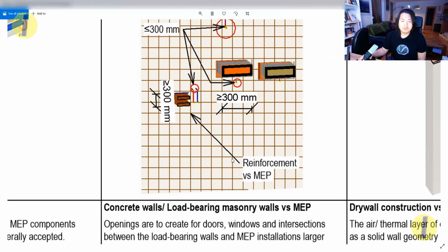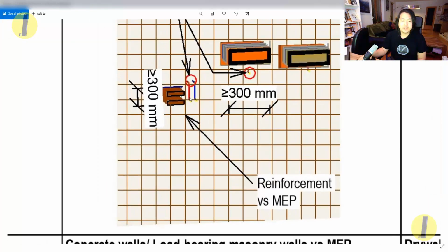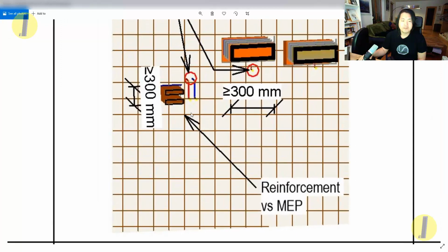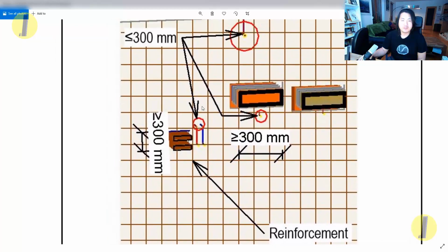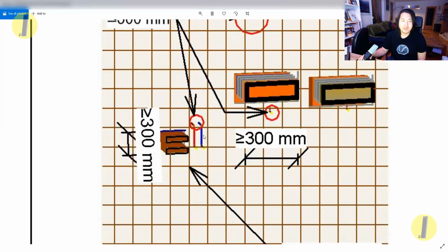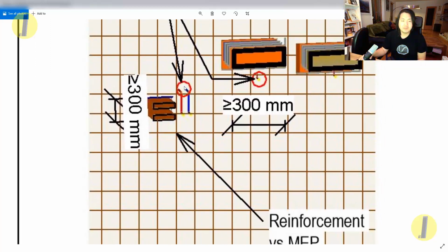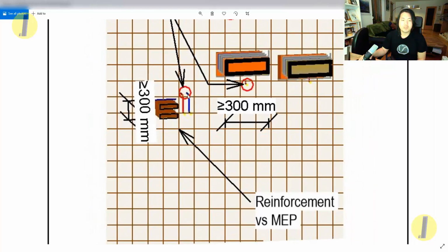And also reinforcement. Even though it's a small pipe, it depends on your model project phase or detail. Perhaps the reinforcement can matter for these small pipes. So if you can detect collisions between 3D reinforcement elements and the small pipes, then you can report them as a collision.